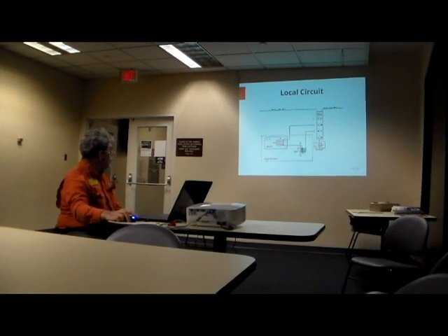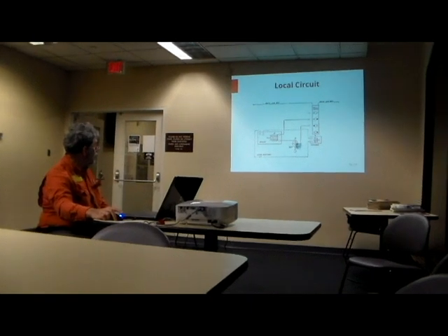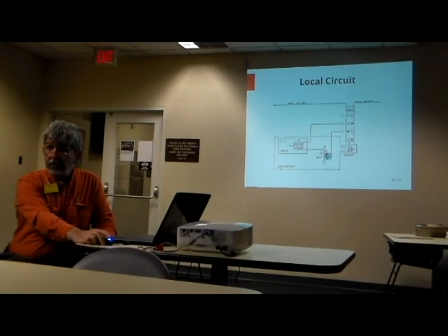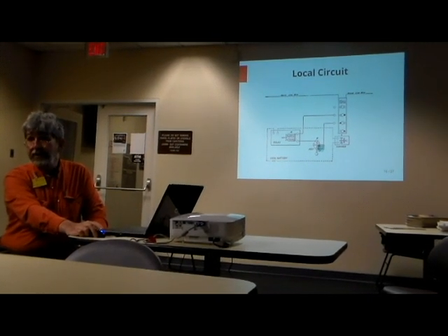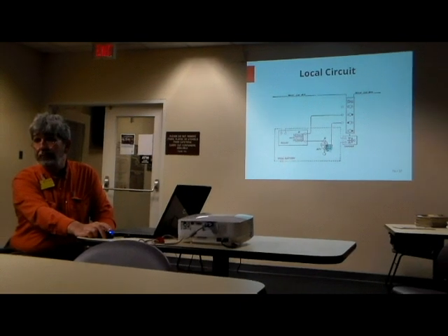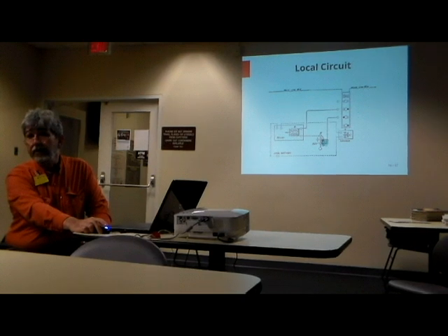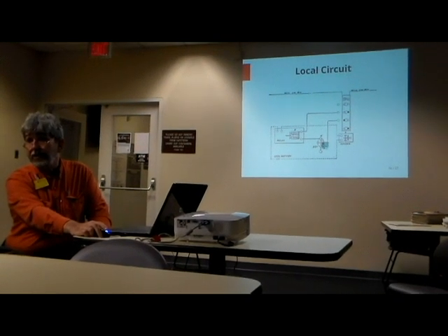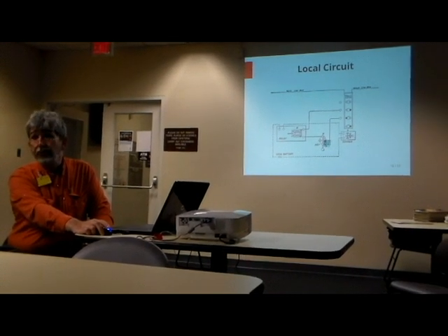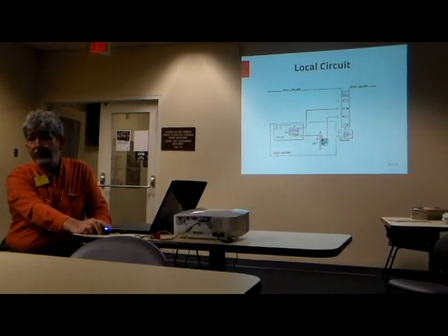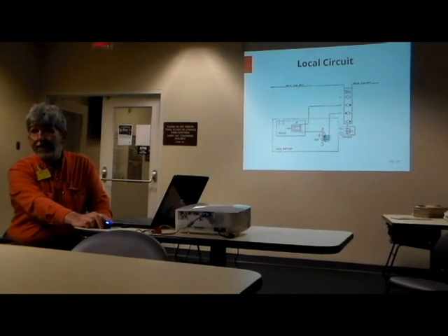So the local battery was one of the single cells I told you about before. And the relay, mainline relays, and almost all of them were mainline, drew only 60 milliamps of current. So the line only had to carry 60 milliamps at a voltage high enough to overcome the resistance of the wire and all the relay coils in series on the line. Each station on the line was a set of relay coils. The keys were so frequently used that they had zero resistance because they were always polished by the motion of use. You didn't have to worry about that.